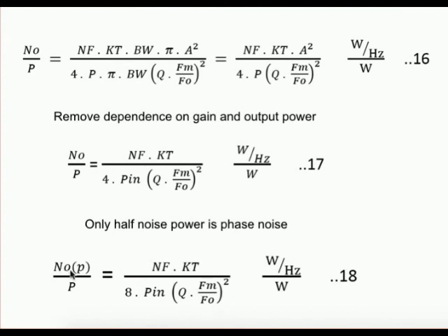This is the phase noise, the density of the phase noise at a specific offset from the carrier. Well, I should say it's really this whole thing here that is the phase noise, because this is the density of the noise that causes phase noise, and this is the carrier power. So it's only these two together that represent phase.